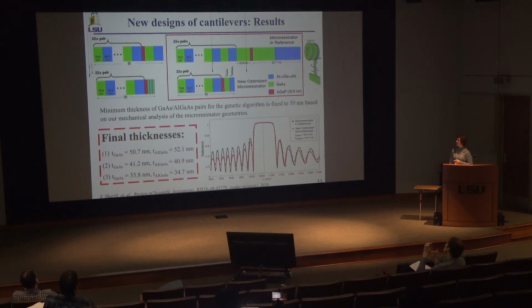First, what I did, I said, okay, let's kick the cantilever out and just transfer one layer of mirror below the indium gallium phosphide and see if we still have 100% reflection, because for us it is very, very important that our mirror has 99.999% reflection, almost 100%. We have never been able to catch 100%, but we are catching 99.999% reflection. So for this design, I said, okay, that's perfect. We reduce almost 355 nanometers easily, and we use one pair of mirror instead of the cantilever, and that way we have a microresonator.